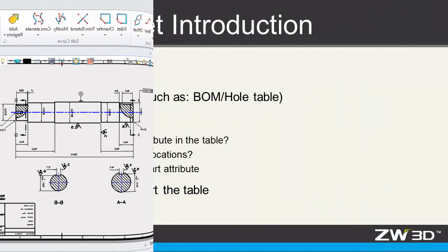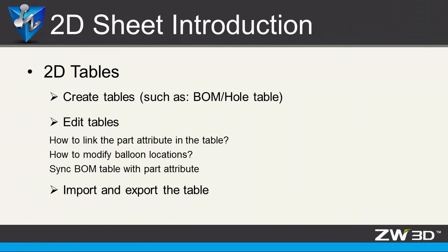The last section is 2D table. We will introduce how to create tables, such as BOM table, how to edit tables, such as modify balloon location, synchronize BOM table with part attribute, and how to import and export the table.